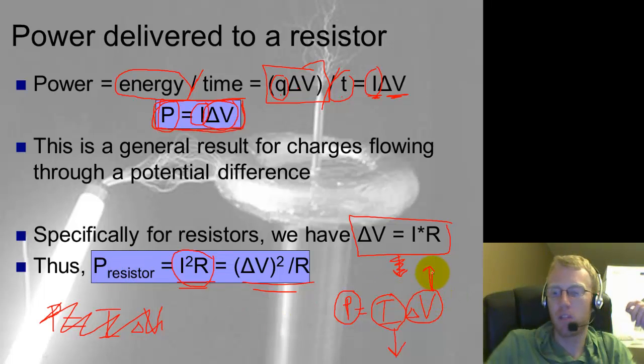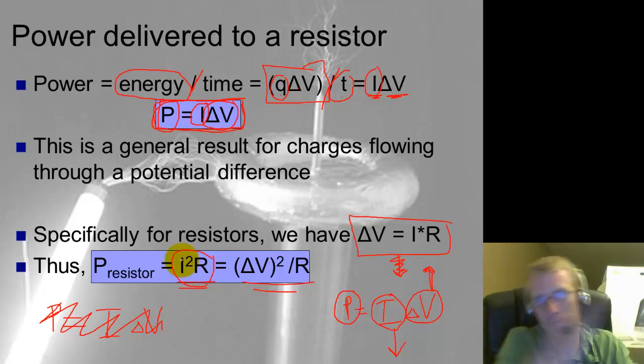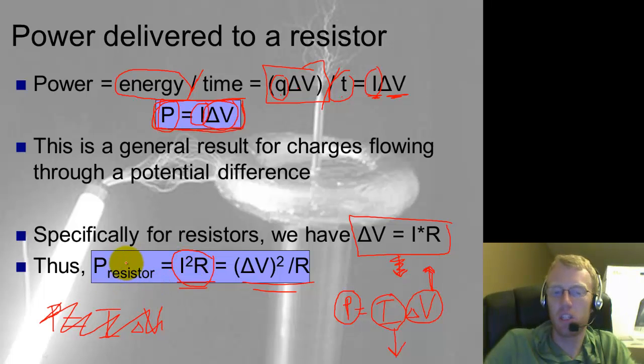But if you increase the voltage and therefore decrease the current, then the current traveling through that resistance is really, really small, and then you square a small number, it gets even smaller. And so the energy that you lose in the resistance of the wires is very small.